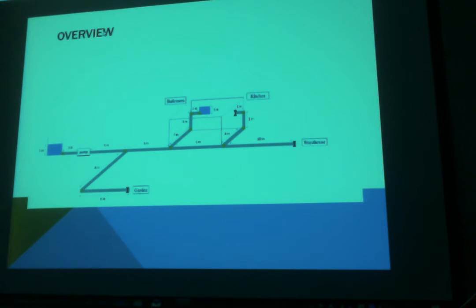Now, as you move away from your pump, your pipes will begin to experience pressure losses due to frictional forces between the fluid and the pipe, bends in your pipe, as well as viscous forces of your fluid.